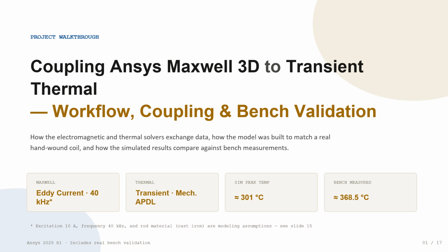Today, we are going to take apart a single Ansys Workbench project, one that couples an electromagnetic solver to a thermal solver, and understand it the way a design engineer has to understand it. Not just how to click through the setup, but what is physically happening at every stage of the exchange between the two physics. This project links Ansys Maxwell 3D, running an eddy-current solution at 40 kHz, to a transient thermal analysis solved in Mechanical APDL.